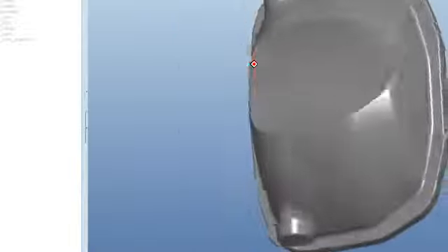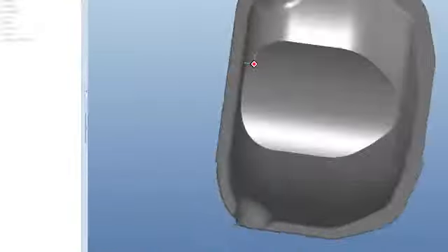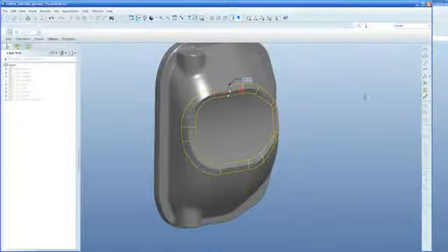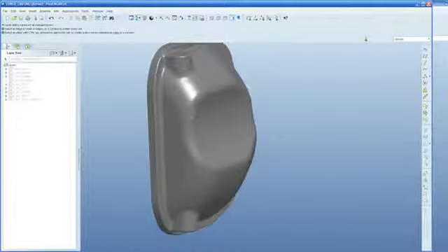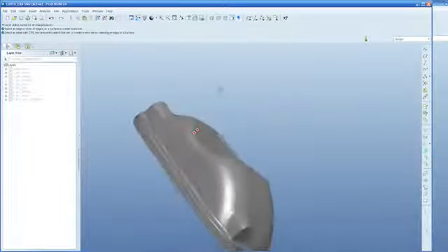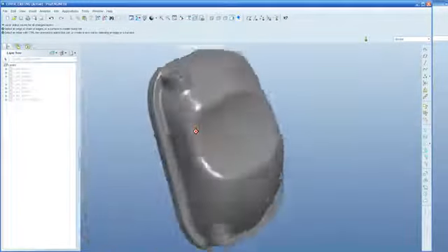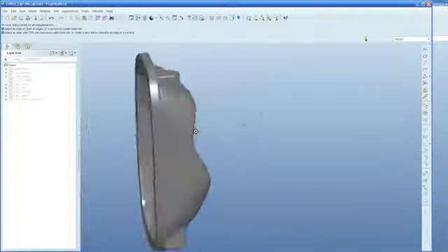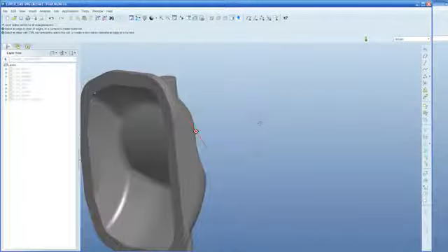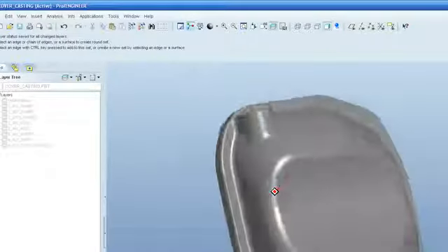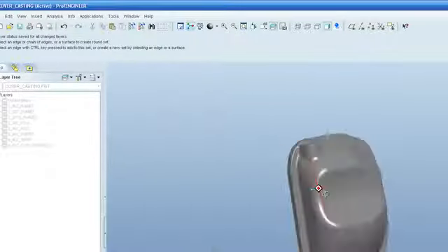Alright, so this is now 100% complete, well, except for a fillet I guess I could put out here. And you'll notice when I go back into my assembly, this is a 100% solid part. I used surfaces to create surfaces and copy geom, solidify to create this dent in my cover rather quickly.